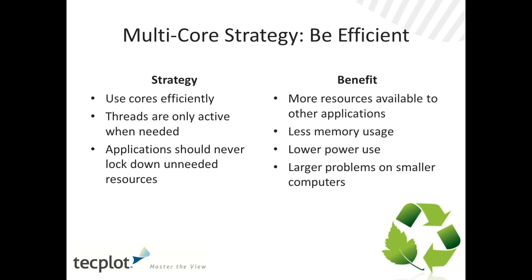To see this, you only have to try running Tecplot doing stream traces. There's an option in the configuration file to set the number of cores you use. You can set it to 1 and compare, and you'll see it scales pretty well with the number of cores.